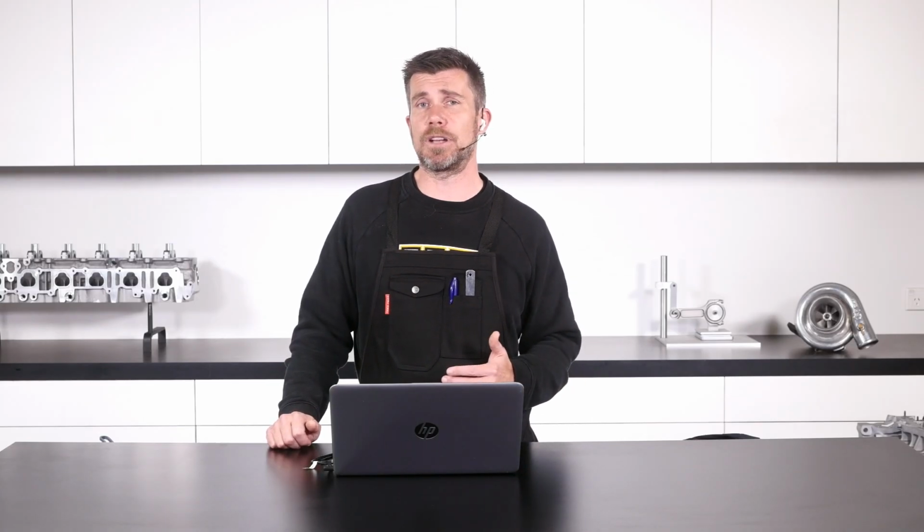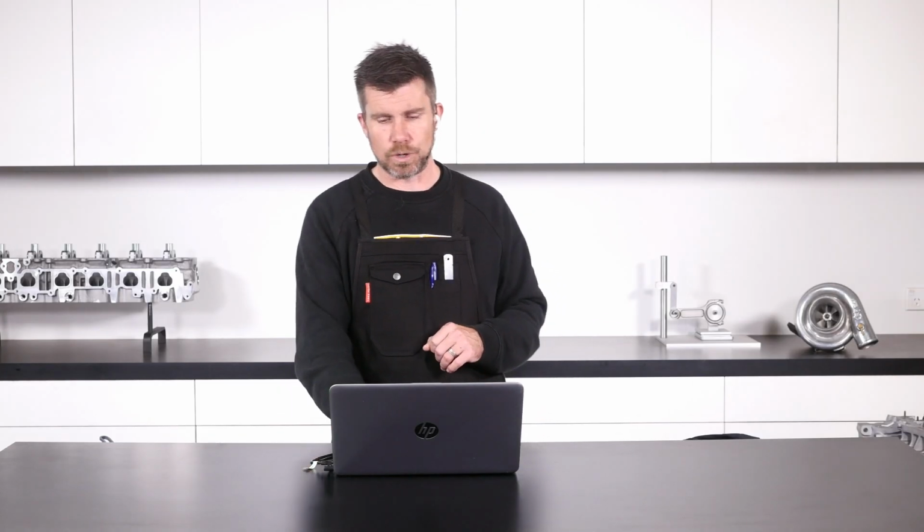overlap. So again, this is where you may want to investigate if you do have very high levels of exhaust manifold back pressure. Again, it'll be a trade-off though, because what you may gain or improve in high RPM where that exhaust back pressure is starting to climb, you're most likely going to be giving away in terms of low RPM performance. But again, the dyno really will guide you with that.